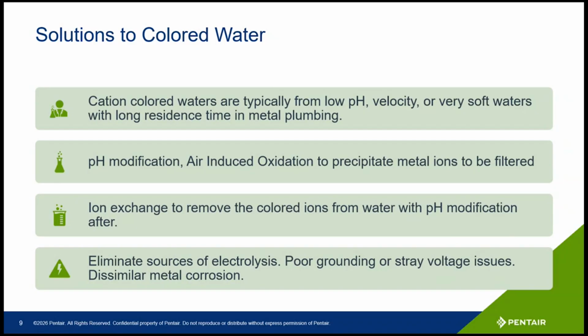Understand dissimilar metals can cause issues, like going from zinc to brass is always an interesting one. If they're not using dielectric unions on the tops of water heaters and things like that, it may impart color to the water after that point. So understand that those issues are there as well. From a treatment standpoint we have to be aware of them, because there isn't a treatment solution for it. It's a correction of an infrastructure issue.